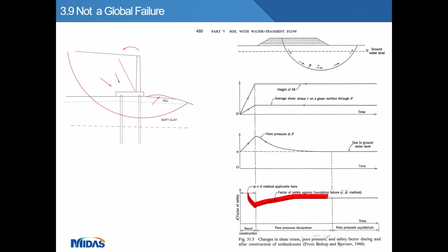We also ruled out that it is caused by the piling installations during the construction of the swimming pool behind the RC wall, a distance away, because the lateral displacement from the installations will continue to happen for months, not after 8 years. And the floor was tile, and therefore rainfall infiltration is not possible.